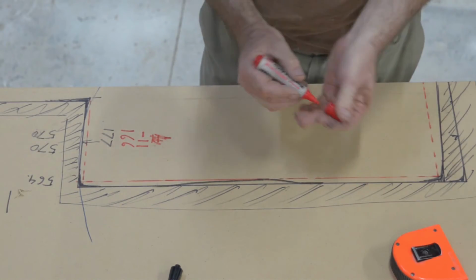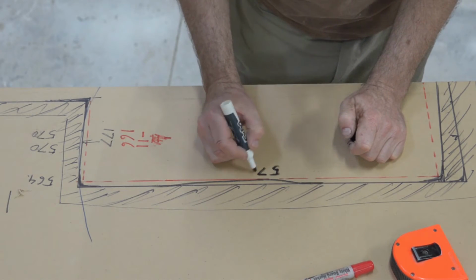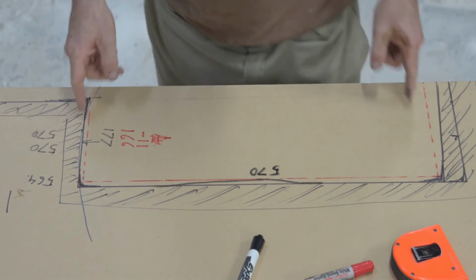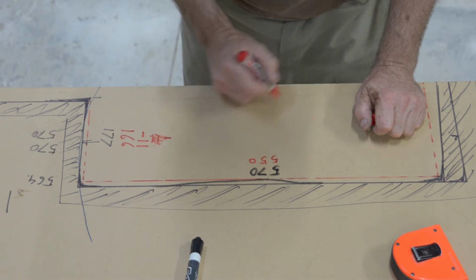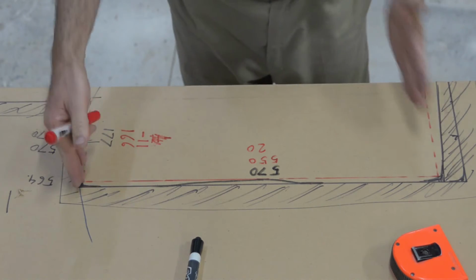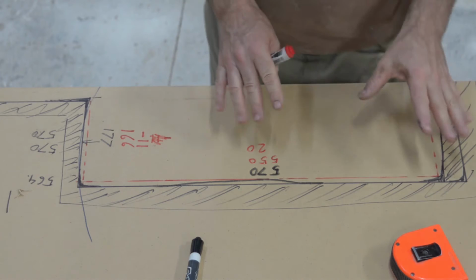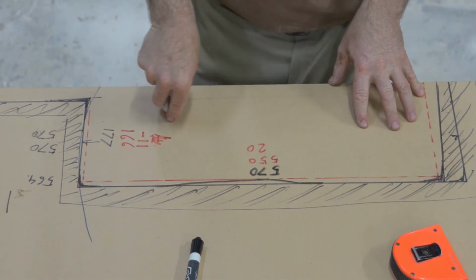So we had expected 570 as a possible, by measuring, say, the front or the middle, but what we ended up with was 550. So somewhere we've lost 20 millimetres, and of course, because you can see it here, you can say, oh, that's where it went and that's where it went. But in the real world, you don't have that option. You just see what appears to be a square painted wall.